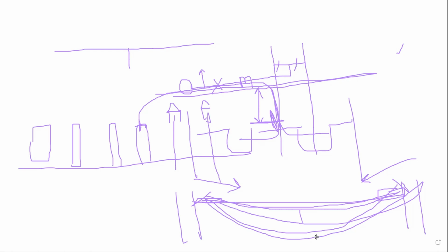But fortunately, here in the substations, the span length, meaning the distance between the supports, is very, very low compared to the transmission lines. So there is not much need to calculate the sag here. Generally, developers will not do the sag calculation inside the substation unless specified by the client. That is also very, very rare.